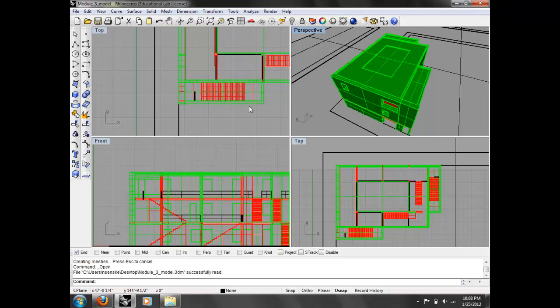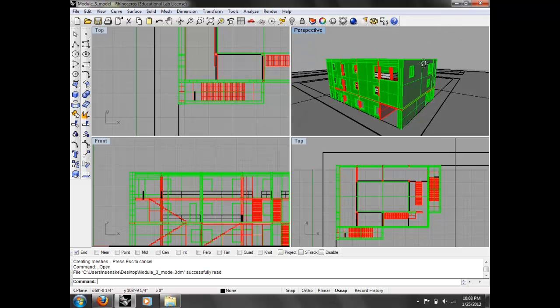And so you need orthogonal views, like plan, section, elevation, things like that, left view, top view, bottom view, in order to be able to understand the relationships of things within the proper scale and oriented to each other properly. Whereas in the perspective, if you designed in perspective, they'd be distorted. It would be hard to find those relationships properly. Okay, so you need to work in multiple views in order to be able to construct things in 3D.